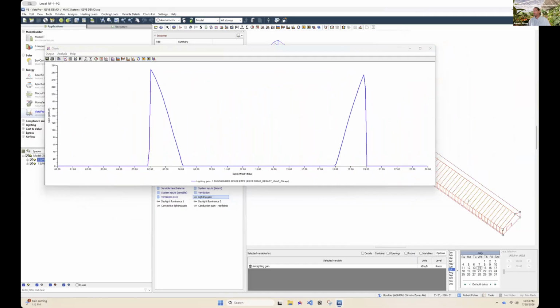If we add in the other building, you can now see that this is absolutely different. It kind of kicks on for a minute, but then it turns off. And the reason it's turning off is we use PAR sensors in our greenhouses. You can simulate PAR sensors in IESVE, which then allows us to understand when to modulate the lighting. If we have full sun coming into this building, we do not need to use lights. The lights turn off.